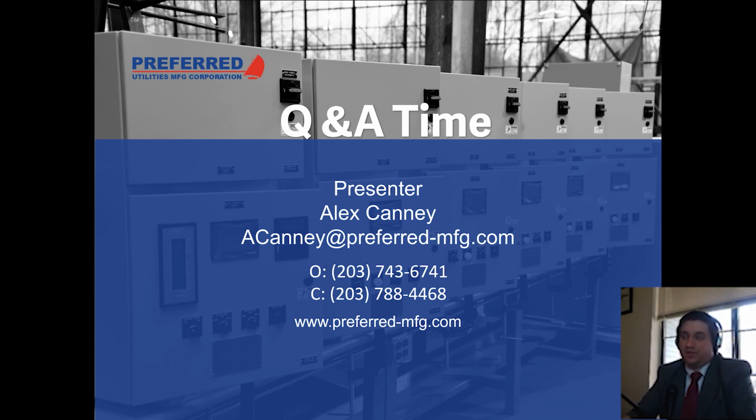And then for the return, that's a good question. I don't know that I've ever had to actually hit a specific point for a return. I would just say that you'd want that return to still be submerged at low level, because as we mentioned before, anytime you're putting fuel into a tank or pulling fuel out of a tank, we want to make sure we're not foaming. We don't want to be just dropping fuel. And we've had some situations in a high rise where if we had an overflow, that fuel can get moving by the time it's at the bottom.